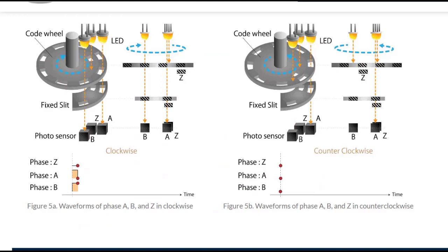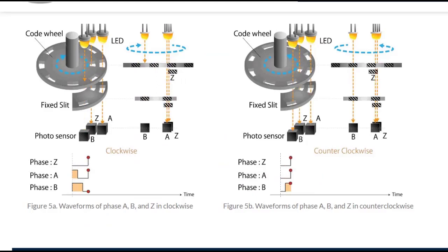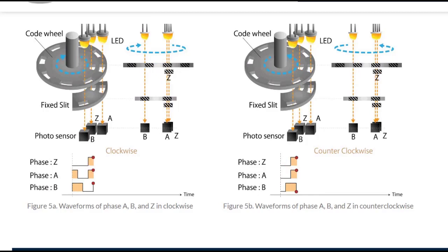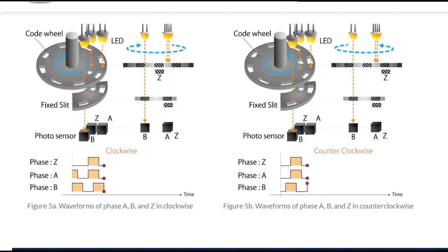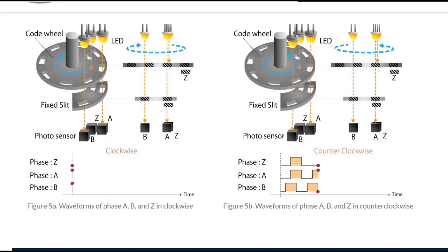The optical encoder consists of a light-emitting diode, a condensing lens, a rotating disc with slits, a light receiver that is usually a photosensitive semiconductor, such as a phototransistor, and microelectronics to process the output of the phototransistor.